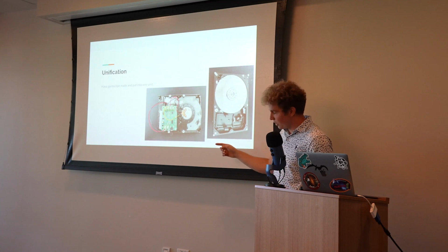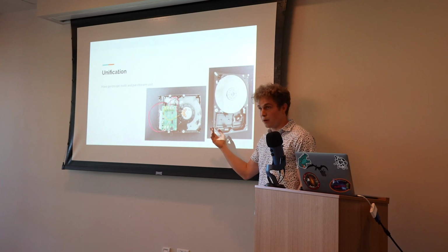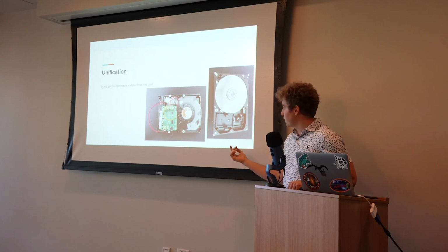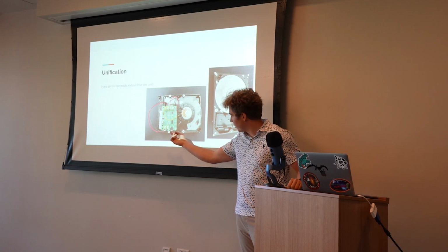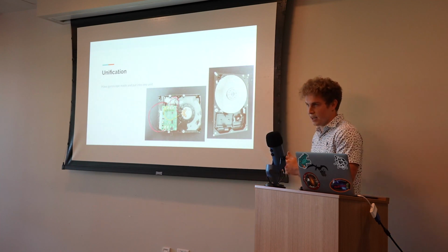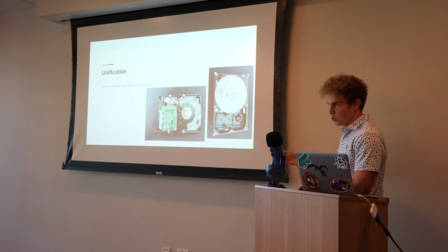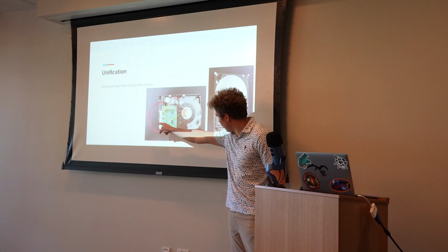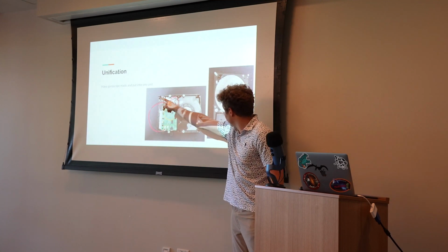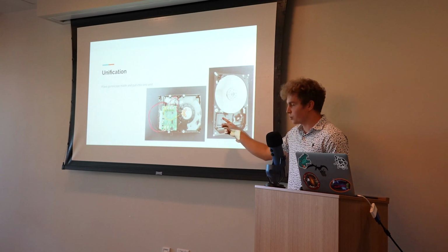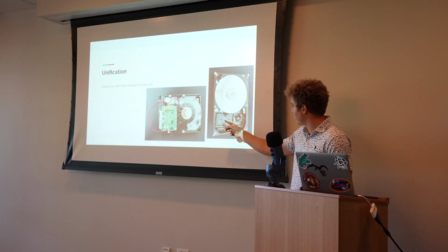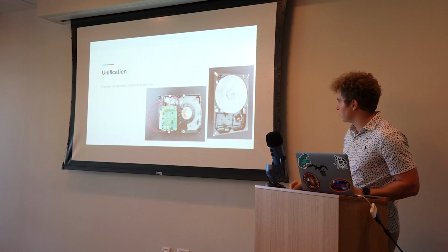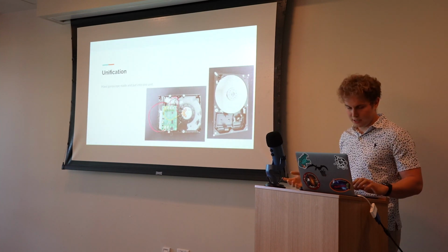The first thing I did here was attach the controller to the body of the gyroscope. I did this using double-sided adhesive tape, making sure to leave easy access to the resistance dial there, which acted as a throttle for how much power you're giving the motor. I then wired the power through and around to the battery, which would be mounted in this 3D printed mount I put here. And yeah, I then tested it and it still worked.